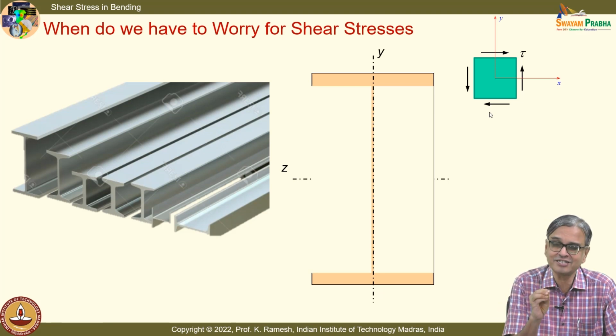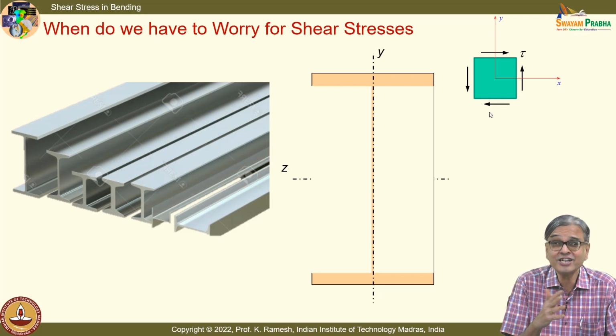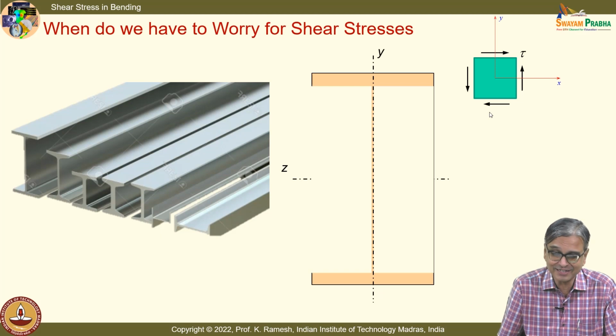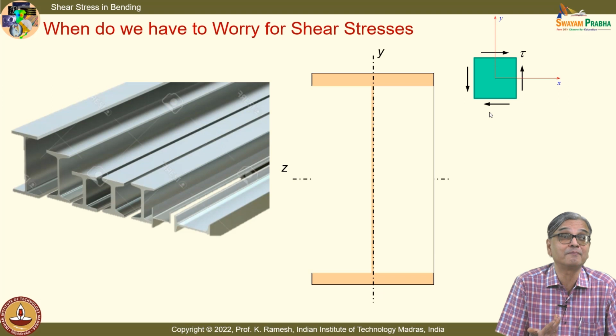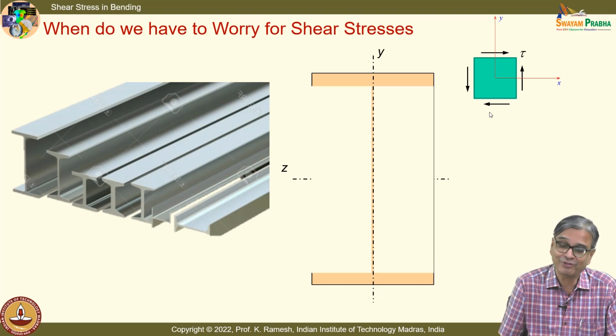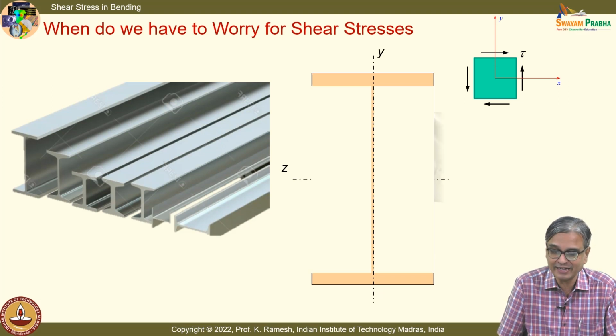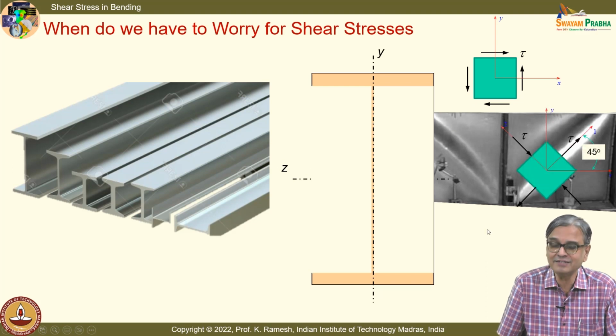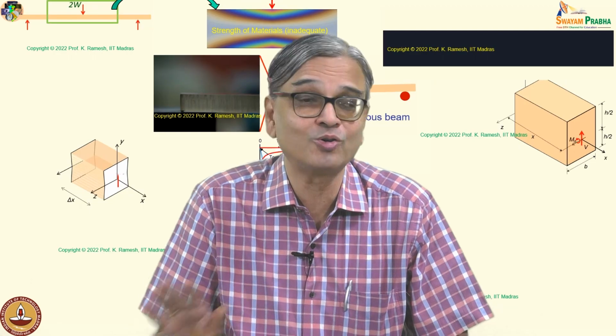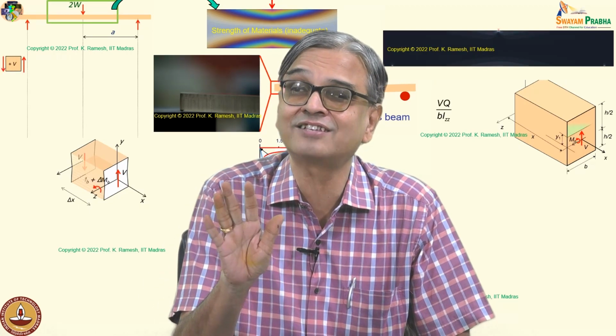A shear stress, pure shear stress, can be looked at as tension and compression, okay. The moment I have compression, what will happen? I can have buckling, okay. I can have one form of buckling which is recorded in literature. You have this buckling, and when I put this at 45 degrees, you see there is a compressive stress developed. So, do not handle shear stress as innocent.